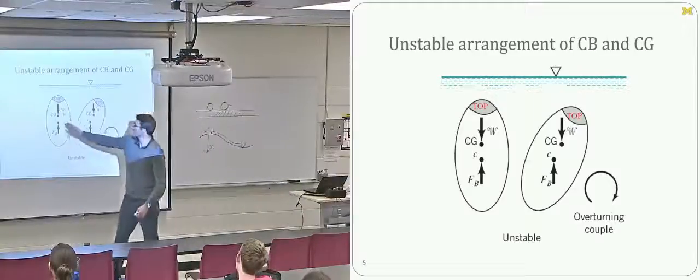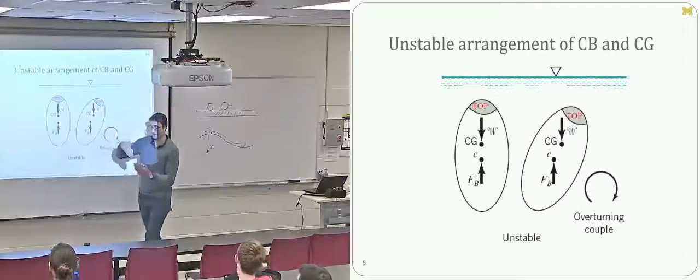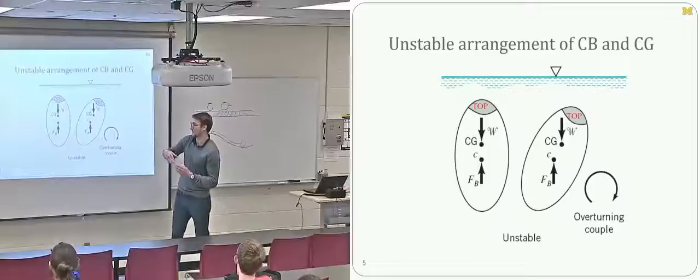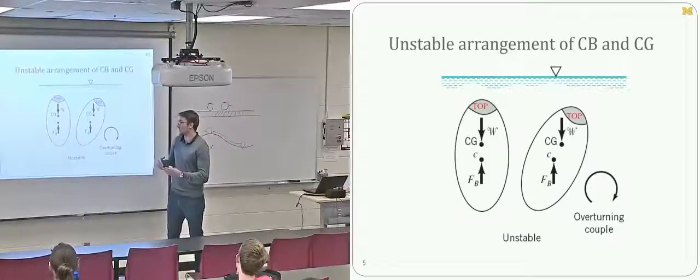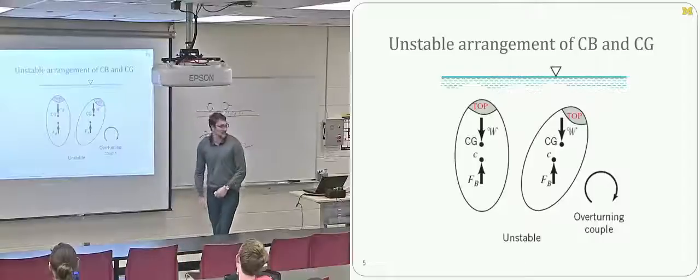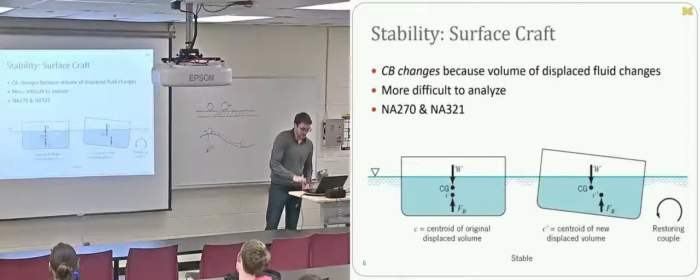In this condition, in a perfect world, it won't move because there's no moment induced on it. The center of gravity and center of buoyancy are concurrent in the vertical direction, so weight and buoyancy simply act to cancel each other and create no torque. But as soon as it's at anything except 0 degrees, no dice.